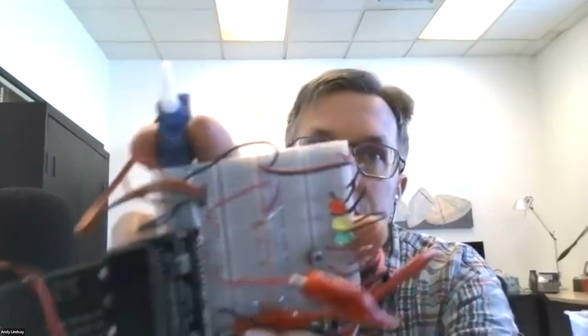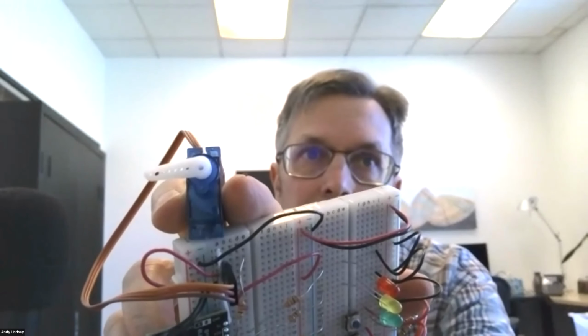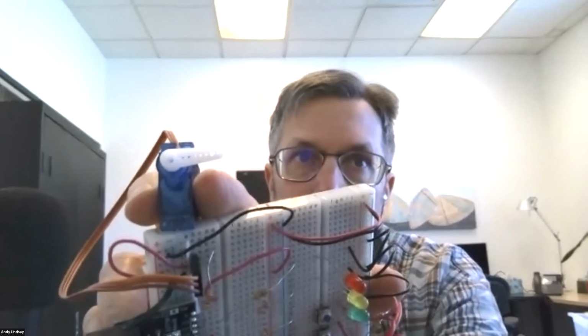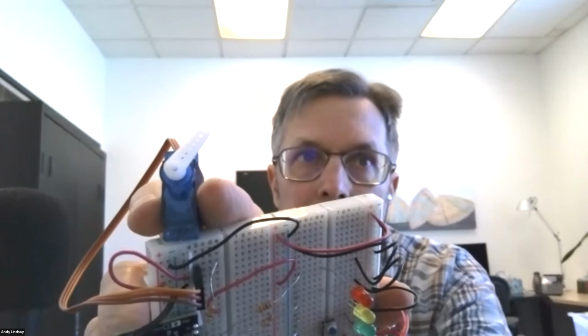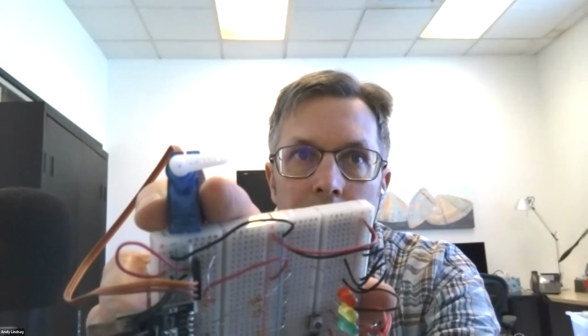So what you would expect to see is, I'm holding the servo up top here, and I have already pulled the white horn off and done that little part that I'm suggesting you skip for now. But after following those instructions of turning it until you feel the clockwise limit, pulling the horn up and off and putting it down so that it faces right, if you do that before running the script, you will essentially see the script point to 0 degrees.